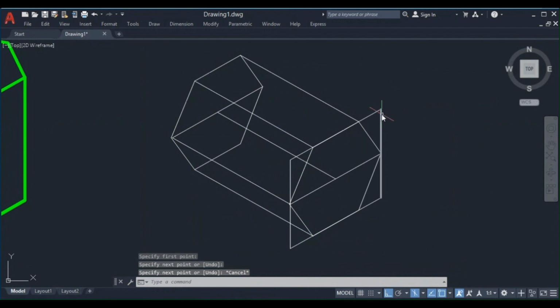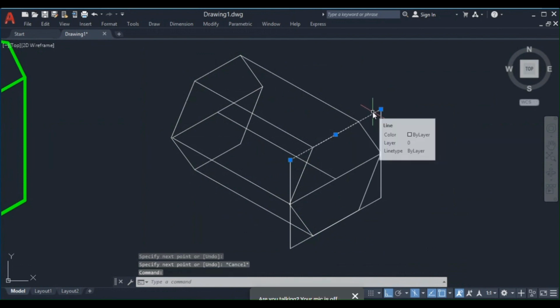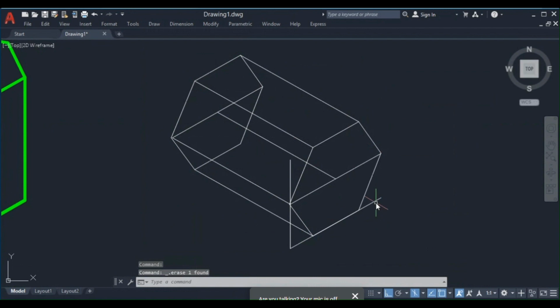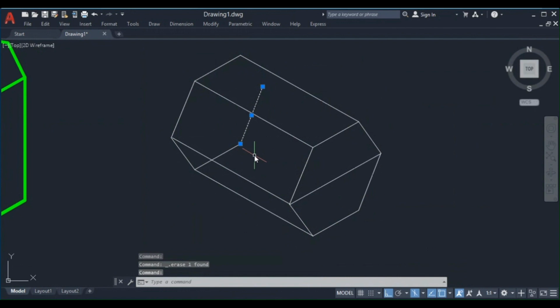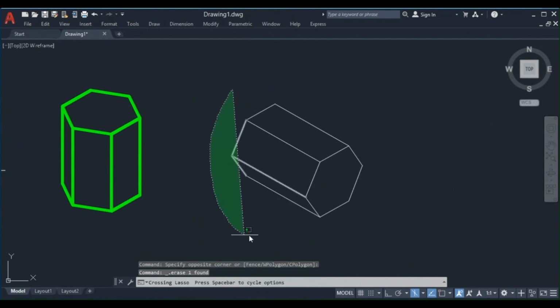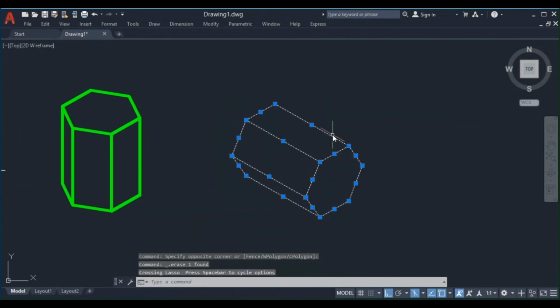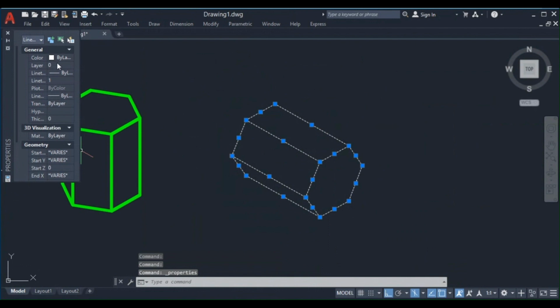Now join top to top. Now I'm removing the portions which are hidden. Let's remove this rhombus for the sake of understanding. Axis also should be removed. Inside this is hidden, and this is hidden, and this is the portion which is visible. Are you able to follow? Yes, sir. Yeah, this is axis perpendicular to VP.